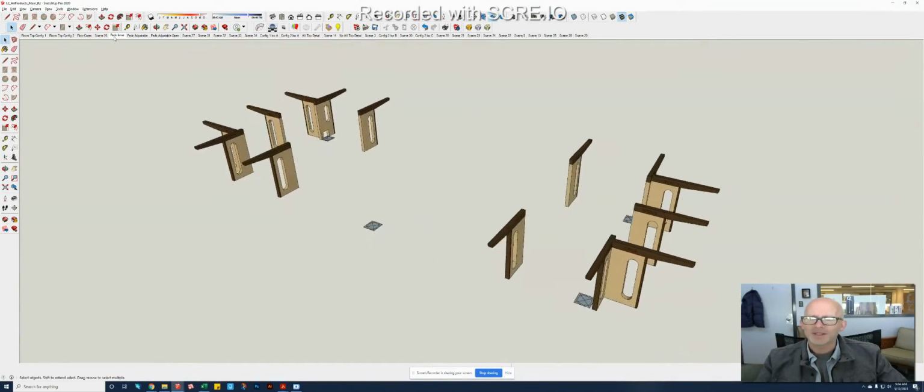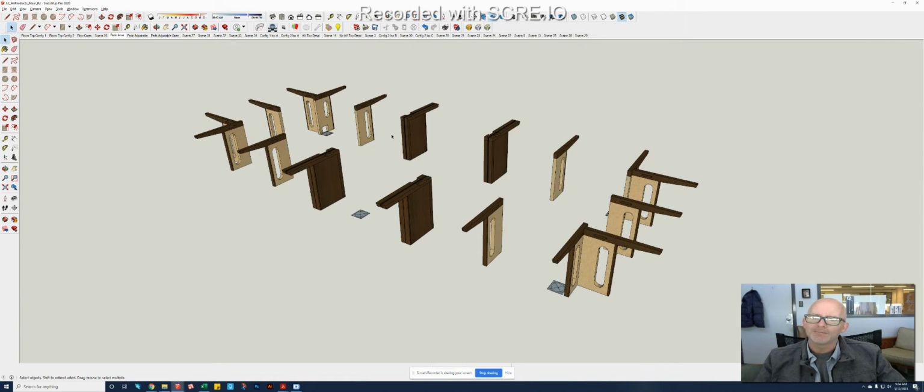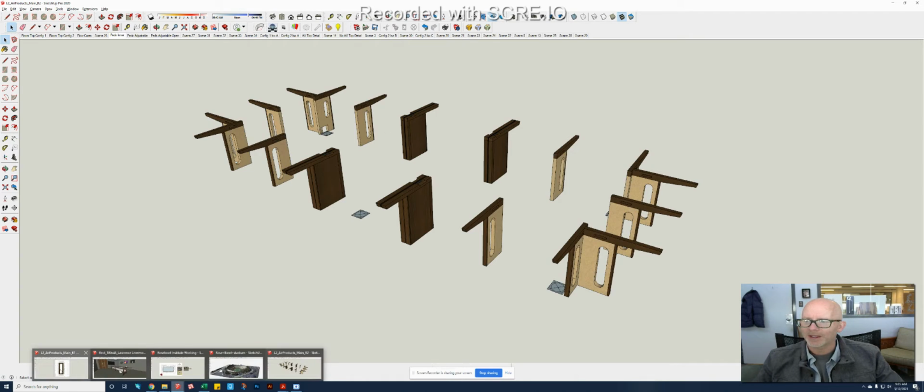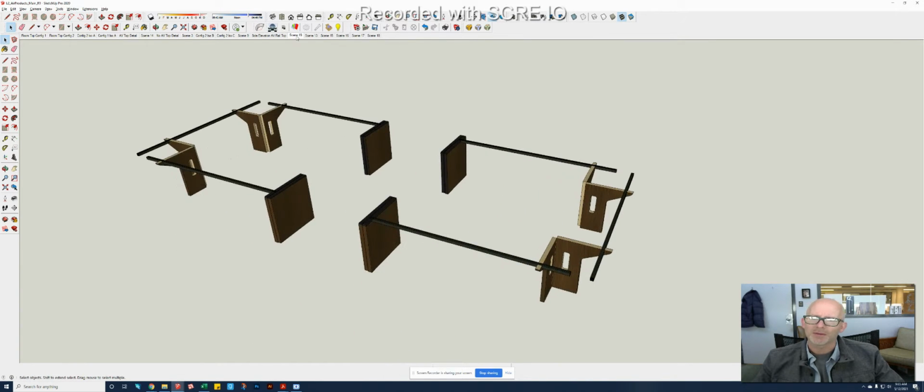This new table design is fabricated from, that ends up being more parts and pieces. So the original design table, if I go back here and we look at the structure, the pedestals, there were less pedestals, but these pedestals also included steel strut support to support the top. As it turns out, that steel strut would be an issue when pushing the chairs in at their maximum height. So we needed a way to sort of remove that.